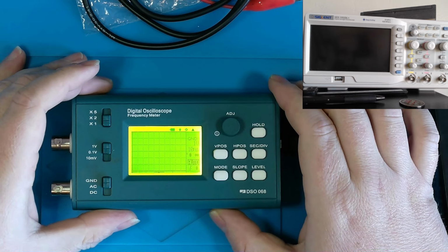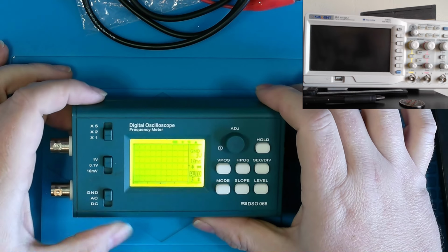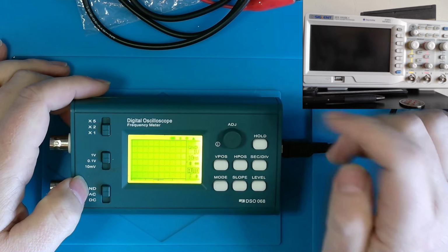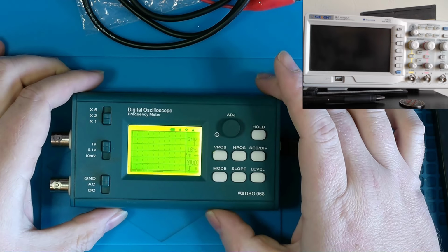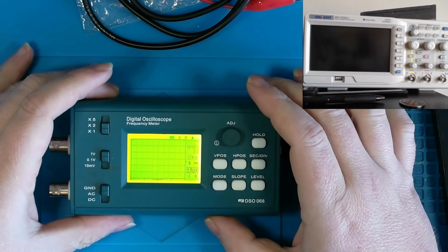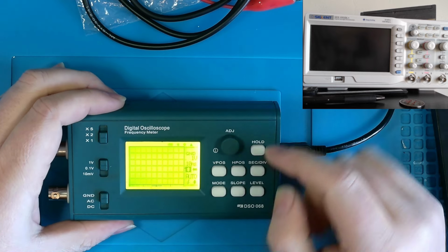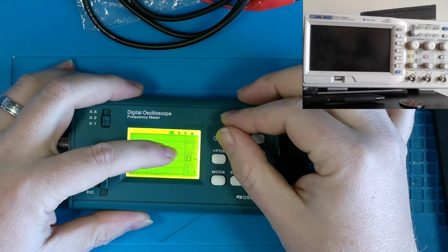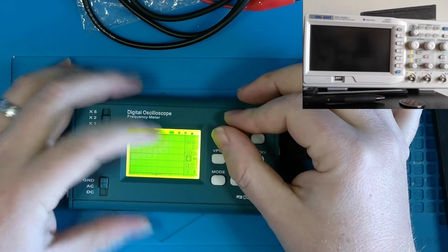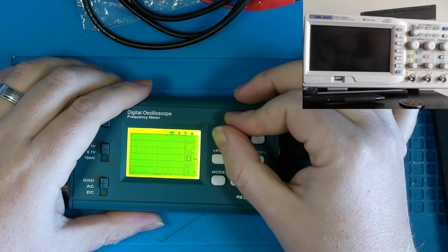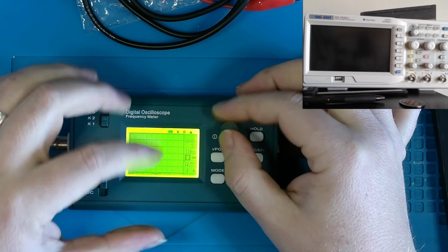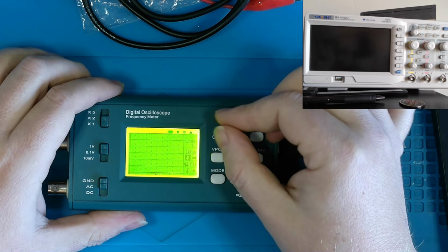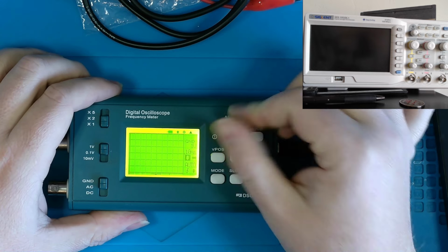Alright, now that we've got it powered on, right now we have it set to ground, and that is basically how you're going to first set up your oscilloscope, and then you're going to set your reference line for ground. On your vertical position, you may or may not be able to tell there's this little triangle here on the right side of the screen that moves up and down, and that's basically going to establish where our signal is going to come across on our graph. I'm going to put this more towards the center. We'll leave it there for now.